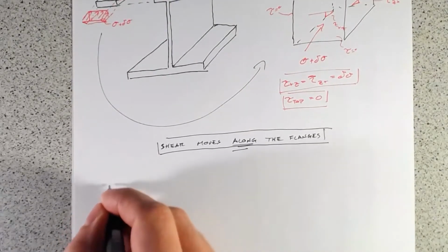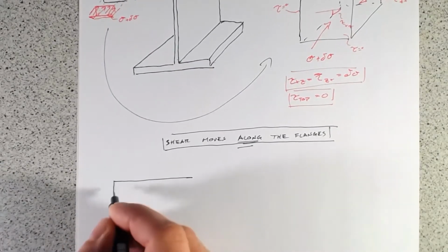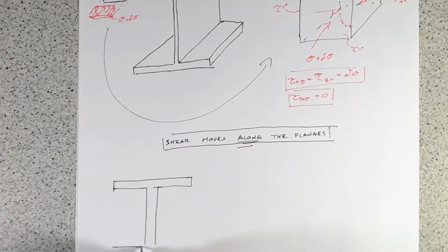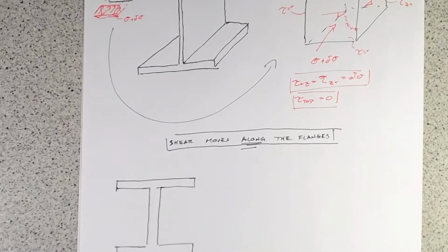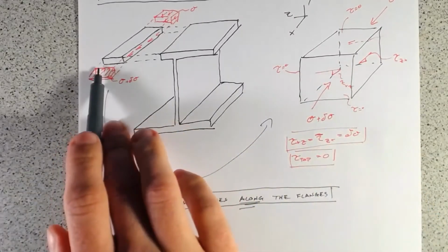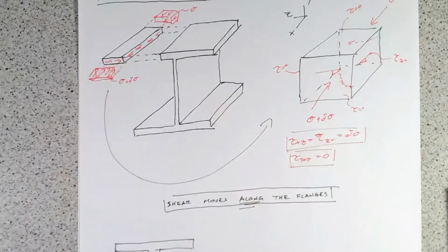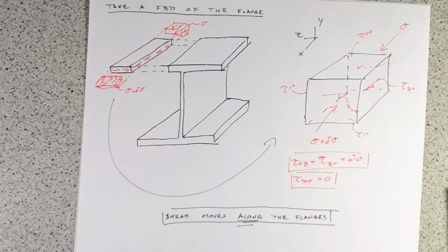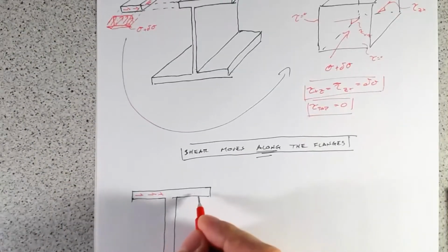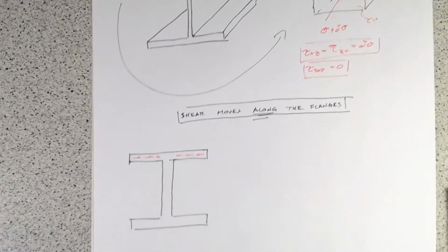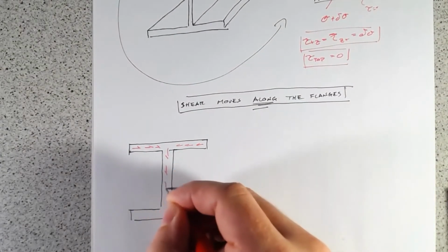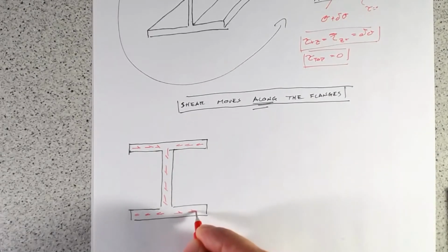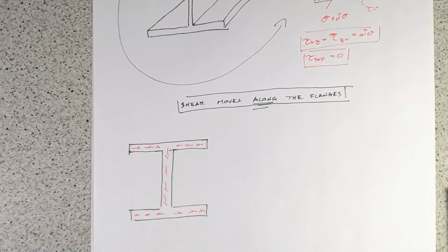So if we draw this out, and see what our shear stress distribution looks like. Because we said that it was going to flow to the left over here, we'll bring that up here and draw a little shear going that way. We're going to have some shear moving this way. Kind of from symmetry, if we do the same thing but come from the other side, we'll see that our shear is going to move in towards the center and then down. We'll work this out with some free body diagrams in a moment, but basically you see that our shear flows through the section.